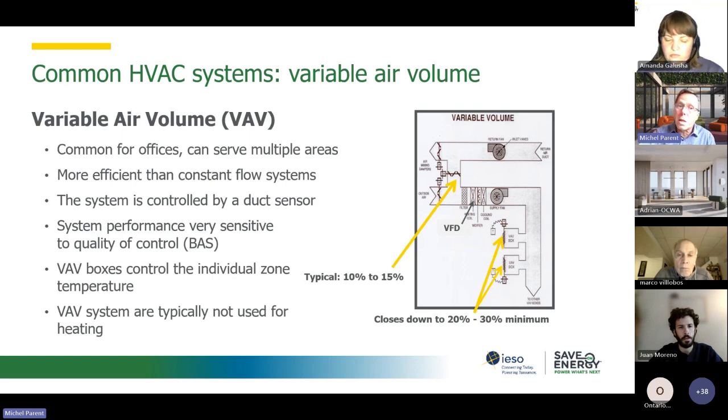And by the way, if you've got a condensing boiler, check the return temperature that you would typically get. And if it's above 140 degrees Fahrenheit, your condensing boiler is not condensing. It just has condensing in the name. It doesn't have condensing in practice. So always keep track of that information. And again, it depends on the level of evaluation you want to go to. If you want to be very precise, you need to collect that type of information. So that's about what you have to document when you walk through the building for your systems.